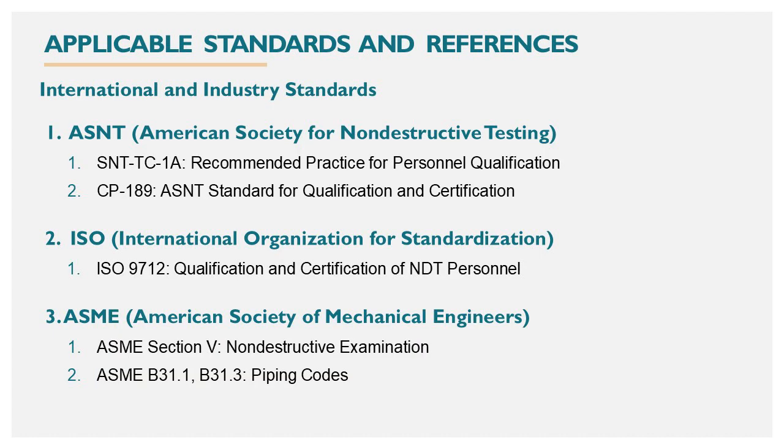Applicable standards and references for non-destructive examination, or NDE, international and industry standards include the following. Number 1, ASNT, or American Society for Non-Destructive Testing, includes SNT-TC-1A for recommended practice for personnel qualification, and CP-189, ASNT's standard for qualification and certification.